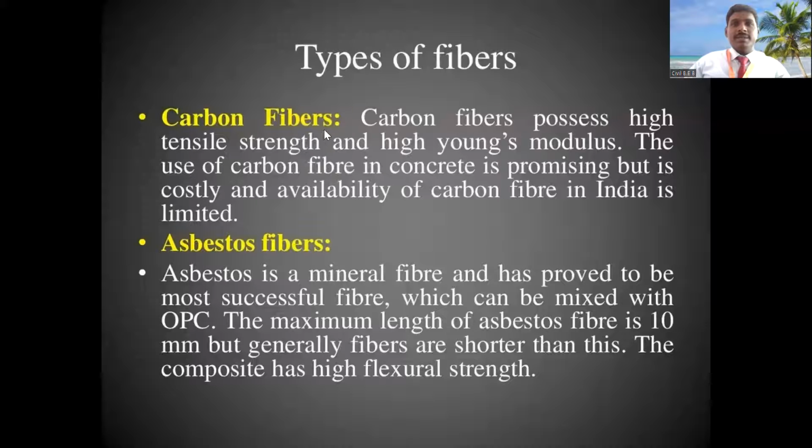Next type of fiber is the carbon fiber. Carbon fiber again possesses high tensile strength. We use carbon fiber for tensile purposes, and it has a high Young's modulus, so the use of carbon fiber in concrete is promising, but it is costly, and the availability of carbon fiber in India is limited.